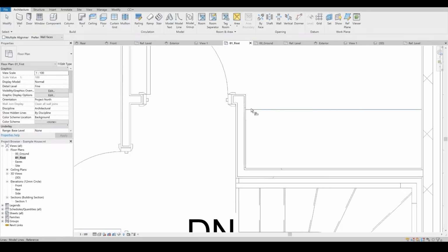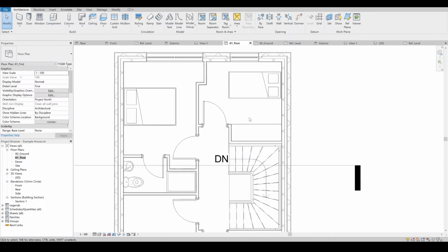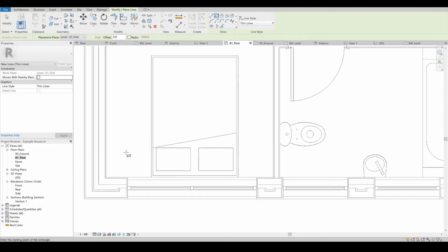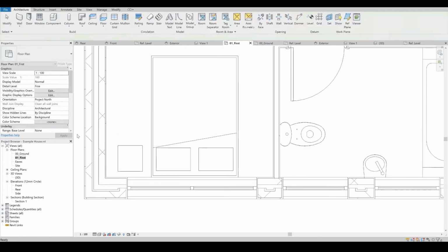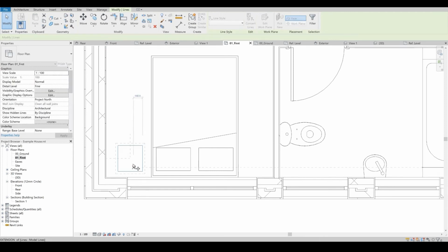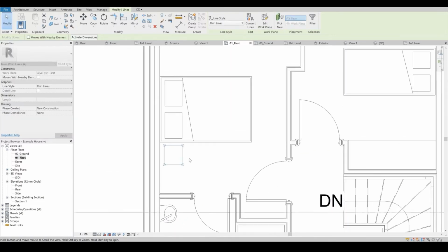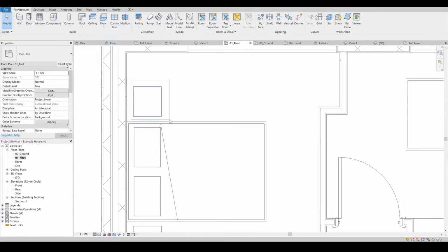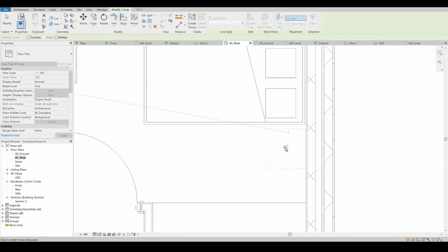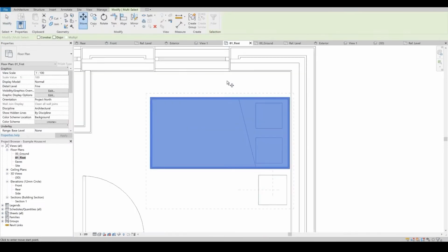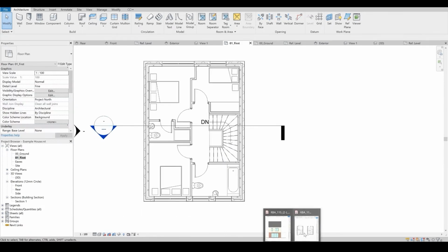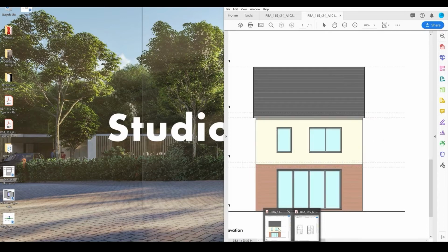So if we use a line, we can then actually bring that down. It increases the size of the bedroom. And even bedside tables, for the purpose of this, we can just drop in as line work. Just for speed, copy that across. CO for copy. Maybe a little bedside there. MV for move. Shove that over there. Okay, it's pretty much the first floor sorted.